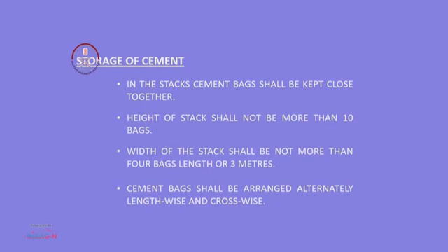The height of the stack also we have to see. More than 10 bags we should not place in one stack. Otherwise, from a loading and unloading point of view, it will definitely be difficult. But more important, the lowermost bag will start to set. To avoid that setting, it is preferable not to place more than 10 bags in one stack. If you place 8 bags, it is fine. In exceptional conditions, you can store up to 10 bags in a stack.